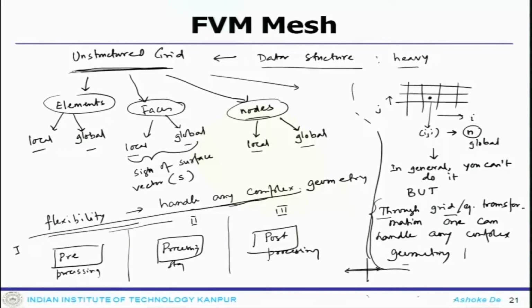Now, you are about to get a solution done for a realistic system. For example, let us say flow through your blood vessels. So, there will be three stages one has to follow. One is the pre-processing stage, this is block 1. One is the processing stage, block 2. Third block is the post processing stage.